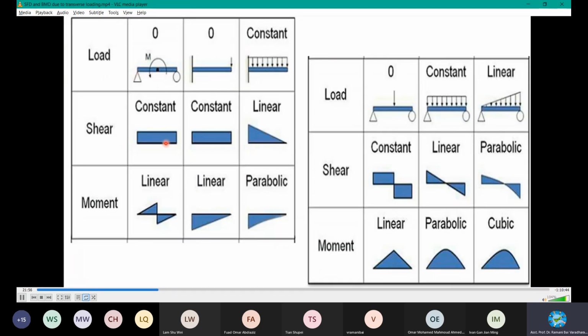Shear force, we are talking about the shear force. When you convert this moment into shear force, there is some value here, a reaction due to this moment, and there is some reaction here. That's why you have the values like this. And then when you come to loading of this type, there is a load, and there is a reaction. When 20 is acting, there will be a 20 in the opposite direction, then only it is balanced. Altogether, you will have a positive value like this.